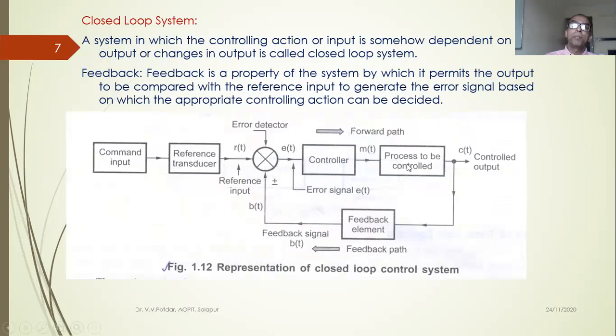So the temperature has to be maintained. The controller will control the temperature. The control output is, let us say, temperature. Thermocouple is, let us say, my feedback sensor transducer. What will the thermocouple do? It will sense the temperature and convert it into equivalent voltage. So that equivalent voltage is my system signal now.